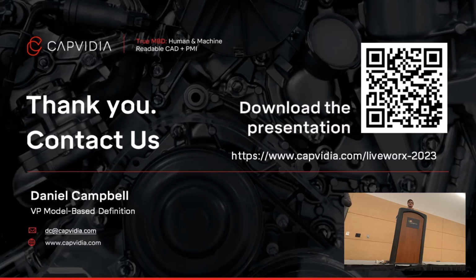The tendency is we're seeing both being delivered as a TDP, a STEP and a QIF. The STEP is intended for use in your in-process design work and for CAM, and QIF is being used for downstream consumption, inspection plans and CMM inspection. But I think we're going to start to see more interest in using it for CAM as well.